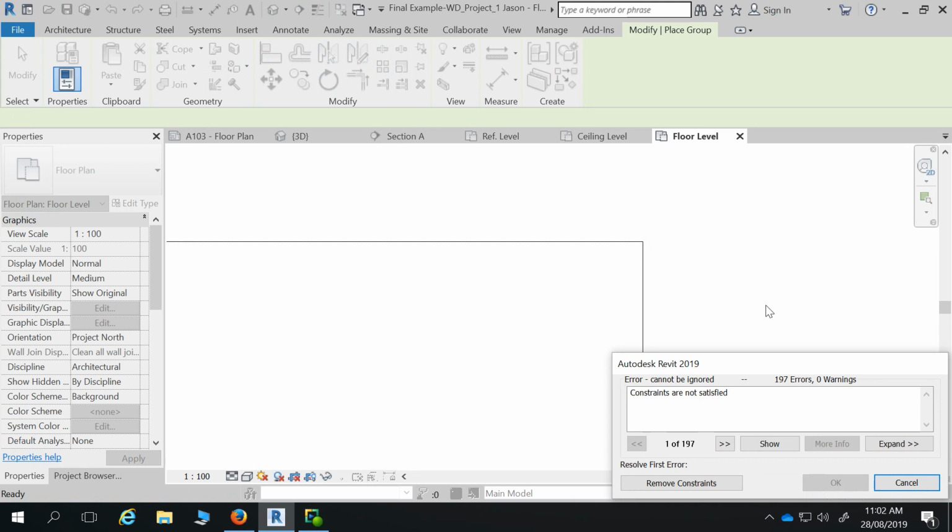You should have a little circle emblem underneath your circle with a cross through it. If you've got that circle element, click. Have a look down at your prompts in the bottom left-hand corner. It might actually be saying origin down there. Does it say it down there? Yeah. So if you have it down on the bottom left-hand side, it's right. Then if you get a constraints are not satisfied, that's absolutely fine. Say remove constraints.